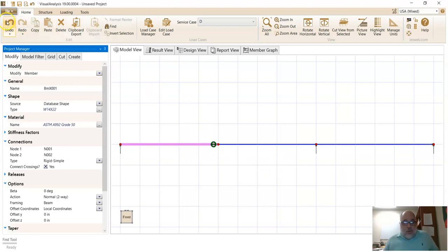I could do that. I'm going to undo, because another option would be to do simple rigid on this member. Again, it's because I dropped the member from left to right, so I know that the first side, the left side, is going to come first. That's why I want simple and then rigid on the other side, and that will work. What I cannot do, what would be a mistake, would be to do rigid simple on both members.